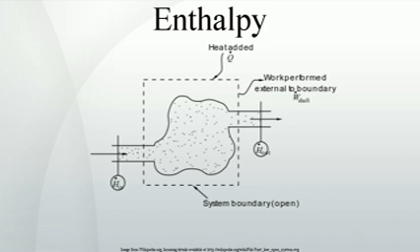Throttling. One of the simple applications of the concept of enthalpy is the so-called throttling process, also known as Joule-Thomson expansion. It concerns a steady adiabatic flow of a fluid through a flow resistance, valve, porous plug, or any other type of flow resistance, as shown in Fig 3a. This process is very important since it is at the heart of domestic refrigerators, where it is responsible for the temperature drop between ambient temperature and the interior of the fridge. It is also the final stage in many types of liquefiers.